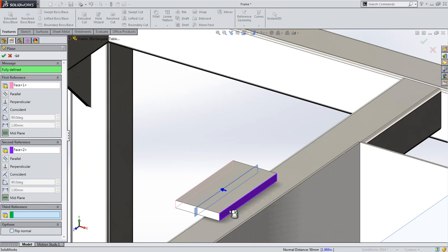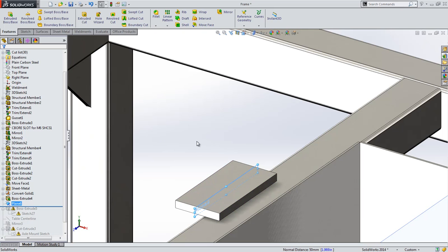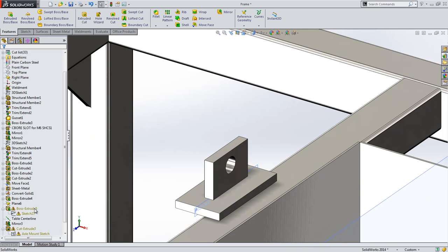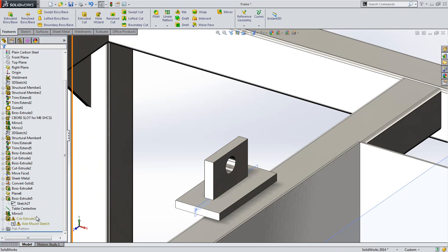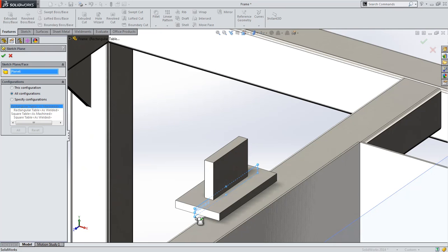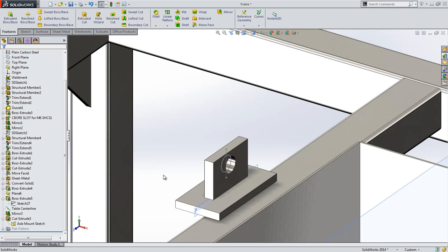When you create reference planes in SOLIDWORKS, you can now control the direction of the normal condition, giving you more control and ensuring that any downstream changes affected by it are in the proper position and orientation. Now, to redefine the missing references we removed previously is as easy as selecting the new plane. And because we set the normal direction, nothing has changed or presented a warning.